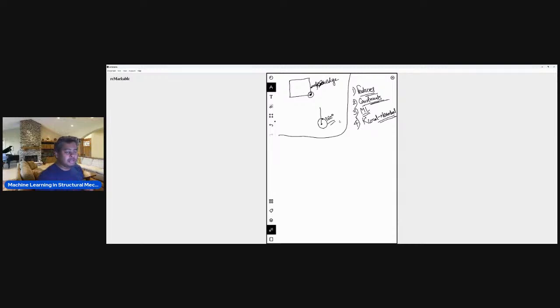It opens up this entire graph theoretical architecture, which will enable the possibilities in terms of how these different k local matrices and their different combinations can work for different types of geometries, if you will. And that will feed to the K global matrix. Once you have the K global matrix, you can of course put your boundary conditions and solve the problem.